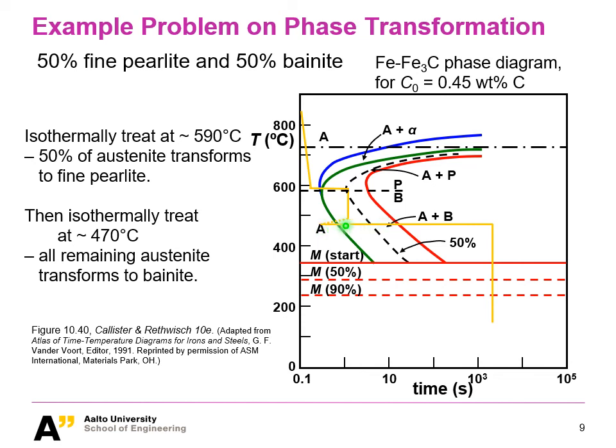So when it reaches this point, you have basically bainite transformation, 50% of bainite and 100% of bainite, and you just hold it further. Make sure you completely cover this time that you converted back. You have to cover this time back by a certain amount, and even with a little bit of safety margin, you make sure at the end you have full transformation to bainite.